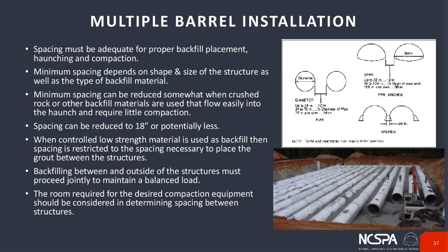So it kind of changes your dynamic because you don't necessarily have the trench wall. You have to get spacing correct and everything like that. So your spacing really must be adequate for proper backfill placement, haunching, and compaction. And the minimum spacing depends on the shape and the size of the structure, as well as the backfill material.